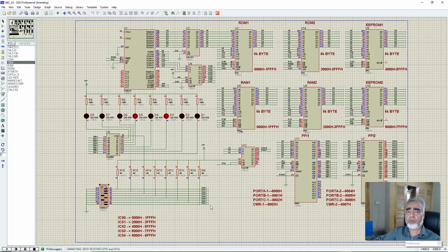So here we have written our first program for the microprocessor based system, and we have learned a new instruction, that is MOVX. Similarly, we can read and write the ports of the PPIs connected in our circuit by using the same instruction, MOVX. The other techniques for assembly language programming are the same as we have learned in our previous sessions. In this session, we have learned how to work with the microprocessor based system. This lecture was the last lecture of our course, learning assembly language programming techniques using the MCS 51 family.